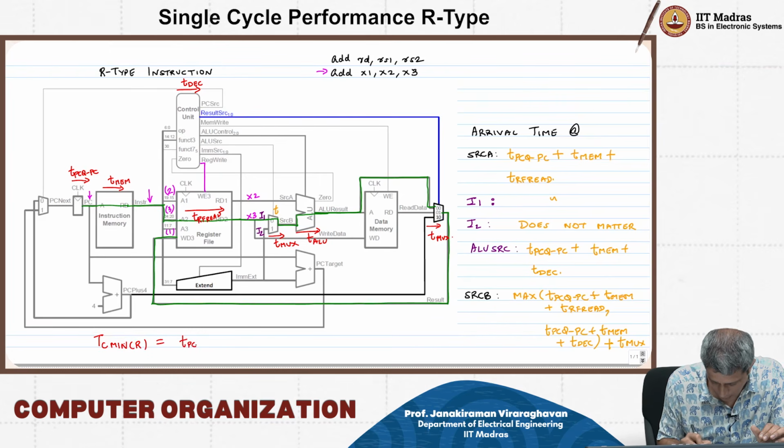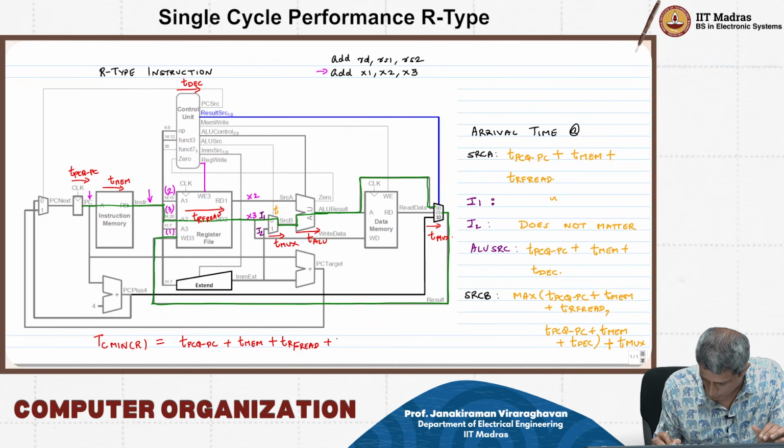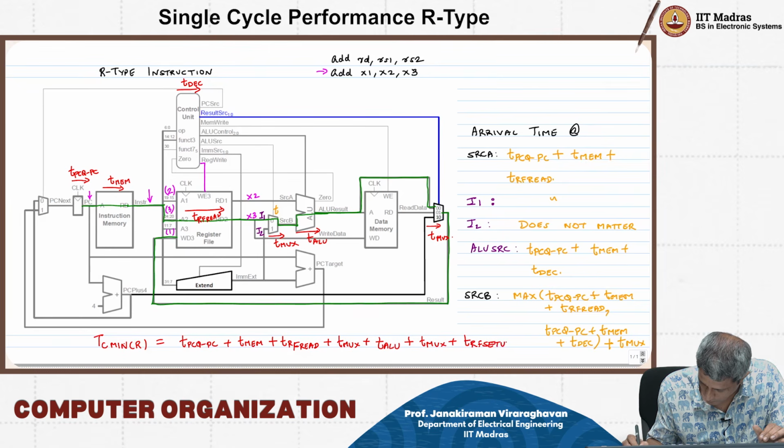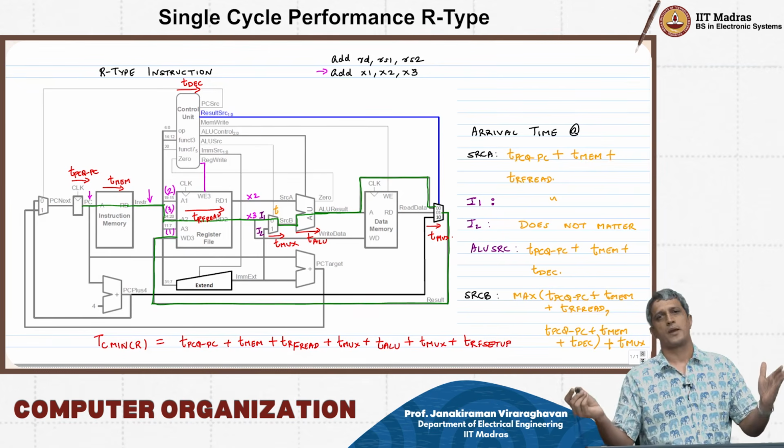It is TPCQ PC plus TMEM, plus TRF read, plus TMUX, plus TALU, plus another TMUX, and eventually you will have to meet the register file setup time.